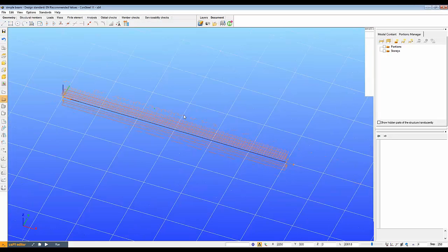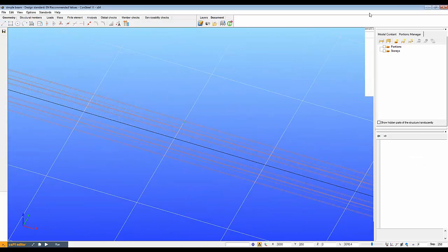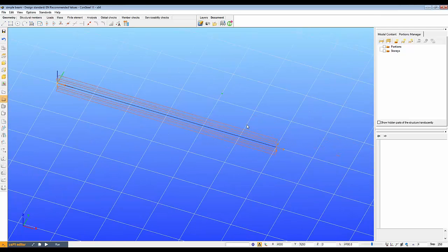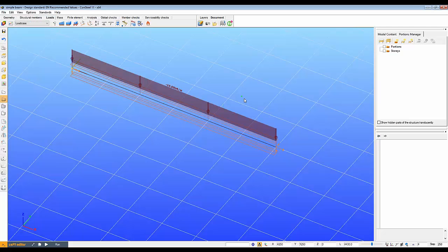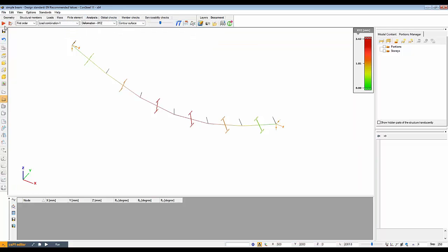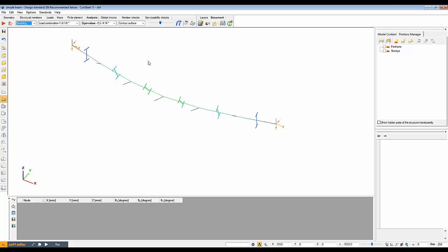Now if I would like to place such a shear field on a beam, I'll show how to do it. First, let's start with a normal 6 meter long beam where there is nothing on it except a load on the top flange, and there is no contribution from any shear field assigned to it. Now if I calculate the critical buckling value, then we can see that this is 4.14. It's a relatively low value. It's an unstabilized, freestanding, simply supported beam.